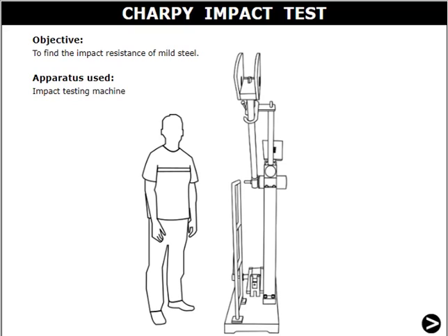Today we will perform the Charpy impact test to determine the impact strength of a material like mild steel or cast iron. We know the impact strength of a material is calculated when we apply a sudden load on it. The resistance offered by that material to the sudden application of the load is called the impact strength of the material. There are two types of impact test that can be performed.